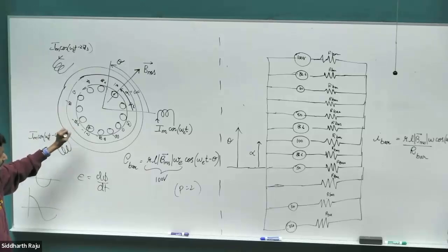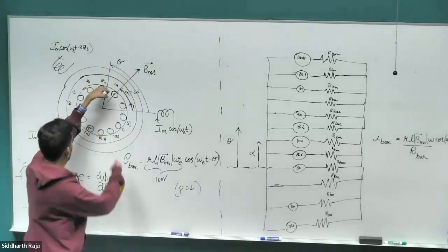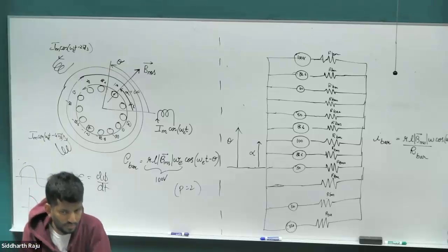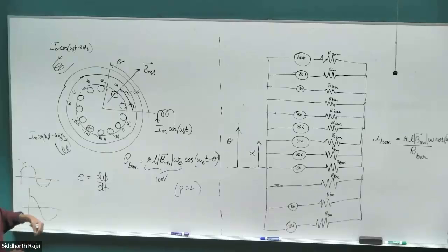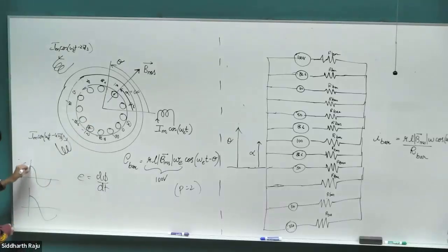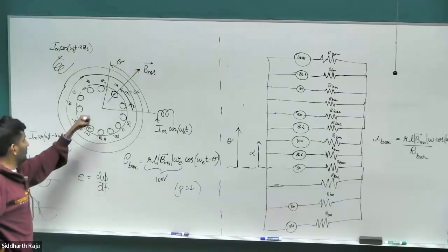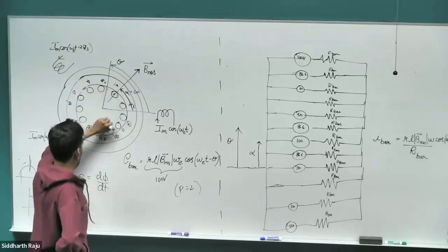Even though the conductors are exactly the same, every single rod is exactly the same, the voltage across them is sinusoidally distributed. Now, as time goes on, as this B field starts to rotate, this whole EMF profile is going to start to rotate along with it. That's like you have 0 to 0 across the loop that you said was the maximum, right? You have 0 volts and 0 volts across the loop that you said was supposed to be the maximum. Yes, the flux linking the loop is the maximum. So the flux is at its maximum, but the EMF is at 0. Any questions? Okay. So as this B field starts to rotate, the EMFs, the space vector, the rotor EMF also starts to rotate along with it.